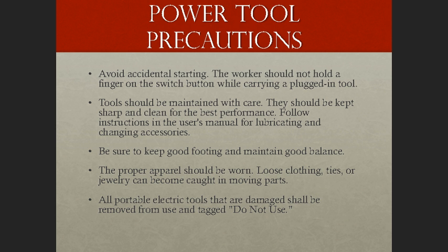Be sure to keep good footing and maintain good balance. The proper apparel should be worn. Loose clothing, ties, or jewelry can be caught in moving parts. All portable electric tools that are damaged shall be removed from use and tagged "Do Not Use."